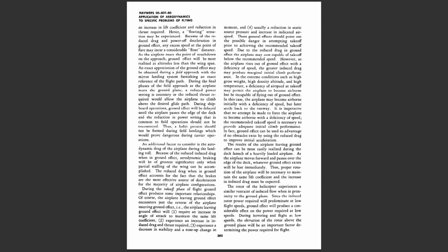It is imperative that no attempt be made to force the airplane to become airborne with a deficiency of speed. The recommended takeoff speed is necessary to provide adequate initial climb performance. In fact, ground effect can be used to advantage if no obstacles exist by using the reduced drag to improve initial acceleration.